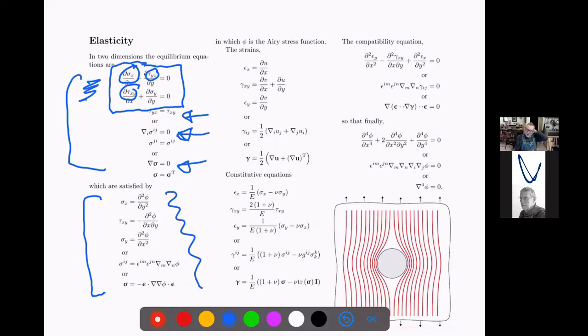And then what you do is to say, well, actually, I've got a curved shell structure, and you then use the area stress function together with the height of the shell, the variation in the height of the shell, to give you the equilibrium equation in the z direction. Anyway, sticking with 2 dimensions, we then have these relationships here